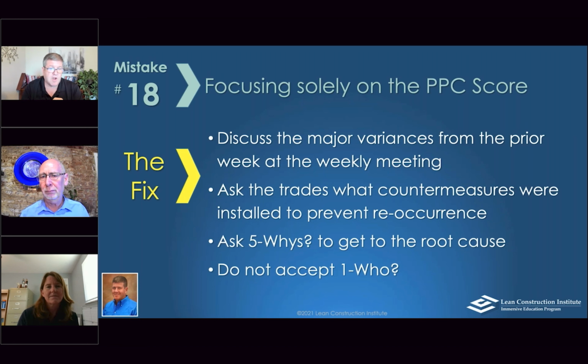Then you move into dry-in. Dry-in's a typical phase. And then along with dry-in, you have rough-in. Those are usually kind of happening at the same time, but you definitely want to pull those separately, like Julie said. And then you'll have finishes, right? Your flooring, your paint, your casework, and then you'll have sometimes startup and commissioning, right? Those are your typical building ones. There may be others. Sean, Julie, do you have anything else to add to that?